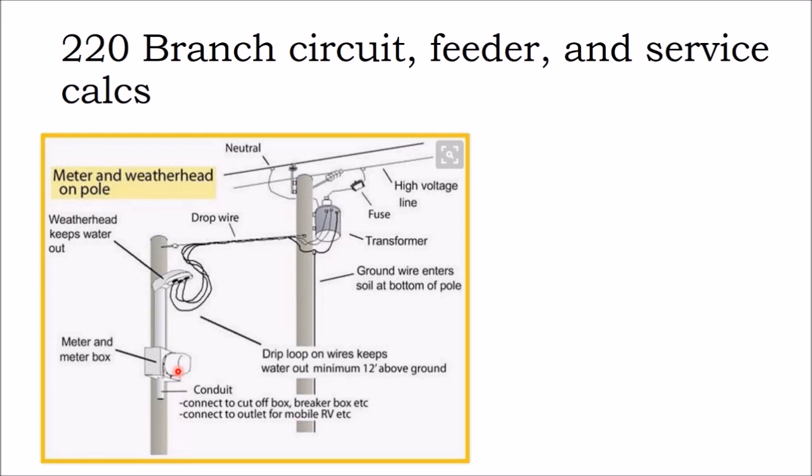So, what you're providing: usually the utility comes out and they will hang a new transformer if need be. If we're establishing a new electrical connection, they connect to the power lines, they transform that distributed voltage into whatever your electric service is. It's a transformer specific to your service. And then the way we do it out in Mississippi is we provide the meter base and the utility meter, although we have to check with our local jurisdiction to see which meter and which meter base they use. Sometimes they're picky about that.